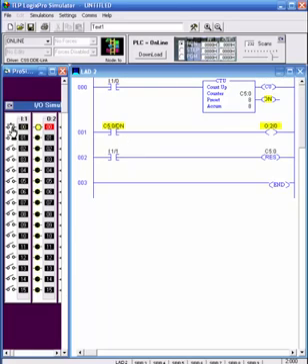And I could keep counting. It'll keep on rolling past that. And there are other bits associated with the CTU. If you highlight that, press F1, the help screen will pop up and it'll tell you about the other bits associated with counters. Now to reset it, I want to push 1/1, which is this button. Watch, I'm going to press it. Ready? 1, 2, push. I pushed it and it reset everything. And now I can start counting again if I wanted to. Fun, isn't it? Okay, so start working on those counter timers.